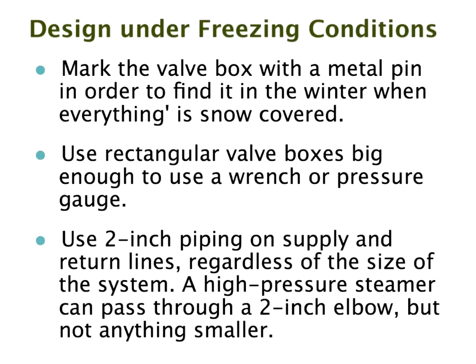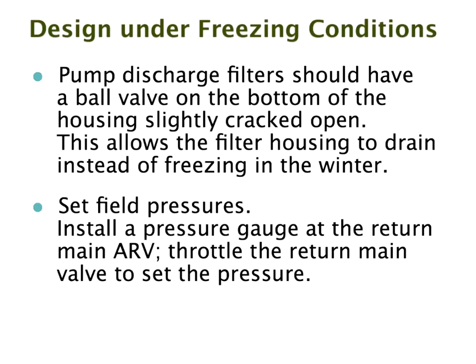Okay, the valve box with a metal pin we've seen in the picture. Make sure your valve box is big enough to use a wrench and to put in a pressure gauge. Most of these air vacuum relief valves have got Schrader valves on them, and you can put a pressure gauge. So you want to make sure you've got enough space to use a pressure gauge when you're testing it in the field. And again, we spoke about the 2-inch line, so you can put in a strainer.